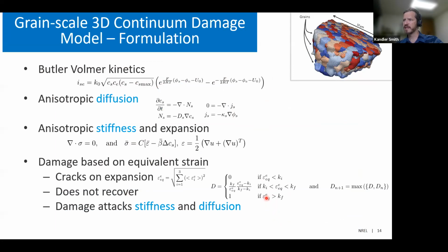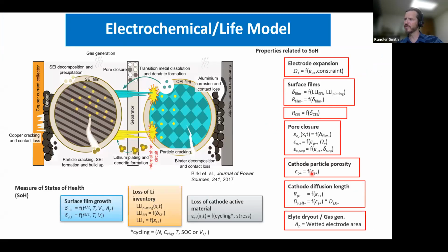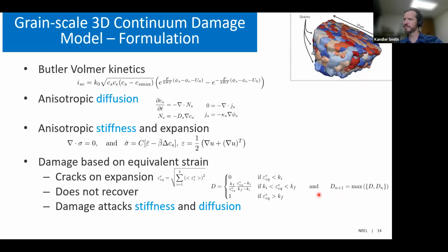So to go a little bit deeper and give you an idea of one degradation mechanism for a polycrystalline NMC particle, unfortunately, each of these deep dives is basically a PhD dissertation or several PhD dissertations, and the models are too computationally complex to say too much about lifetime, but they can tell you things like effective properties, like the effective diffusivity of a cathode particle that might go into this macro homogeneous model.